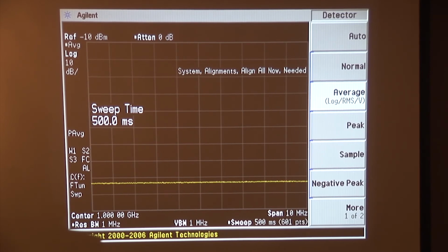Oh, and in fact, I'm going to momentarily turn the signal off on the generator for the moment. We're going to turn on the amplifier, and I'm just going to push the connector on and off here. Here is the spectrum analyzer noise floor with no amplifier on it. Now, I've turned on the amplifier. There's no signal input on the amplifier whatsoever. So now this amplifier is generating excess noise, which in decibels is equal to its decibel gain level plus its decibel noise figure level.